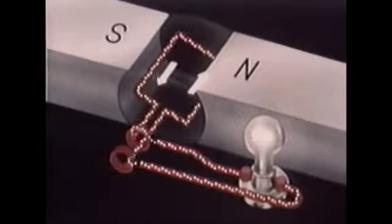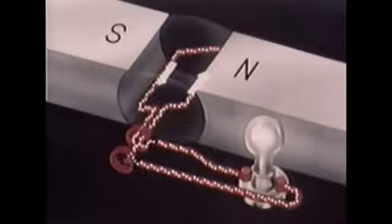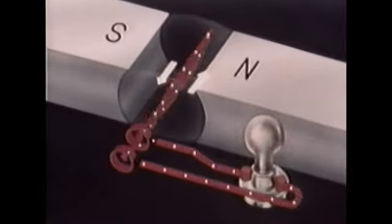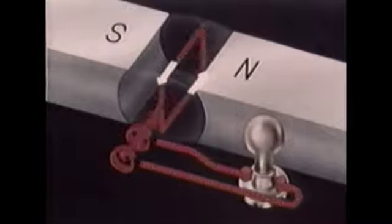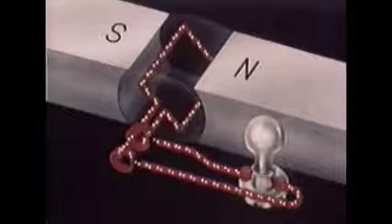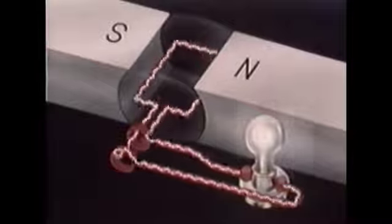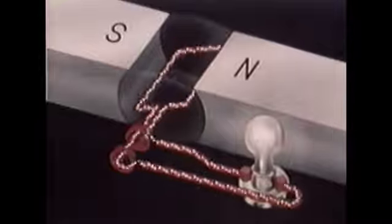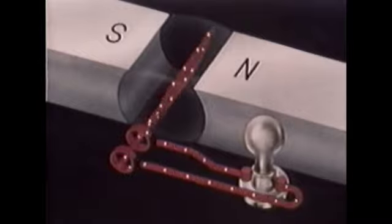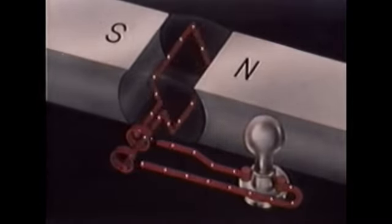After the coil passes through the position of no current flow, the previous downward side moves up, and the previous upward side moves down, thus reversing the current flow in the external circuit. This, then, is alternating current, a flow of current in a circuit which reverses direction periodically and is continually varying in strength. The current flow is caused by an induced alternating voltage.